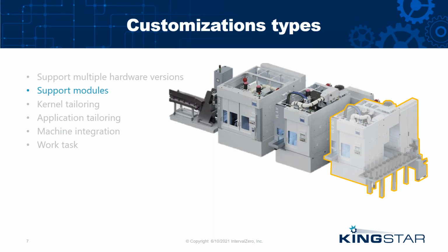But nowadays, with the new technologies, it is possible to do even better. Controllers can detect which modules are connected without the need for any customization or updates. It will detect and identify the modules, and adapt itself by loading the corresponding software for all the attached modules. It is now even possible with protocols such as EtherCAT to add modules to a running machine. This means that the controller and software can be added and applied to a new module while other modules are still processing.